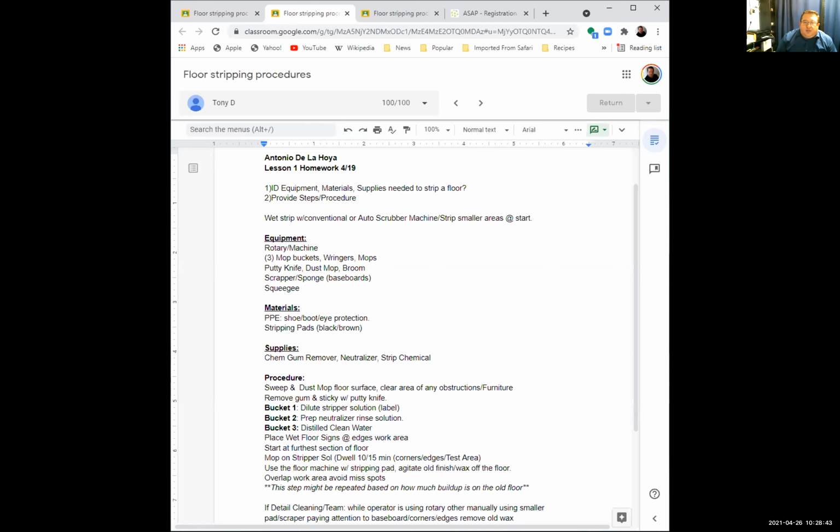So let me wrap up with the school on the MP room. Here's a way that you can learn how much square footage there is. There are two ways to measure it if you don't have a measuring tape and you want to cheat. They're a little more difficult, but I'll tell you the tricks. If it's VCT on the floor, VCT is a standard 12-inch by 12-inch. Count the tiles on the wall one way, count the tiles the other way, and multiply them. That gives you your square footage, because each tile is 1 foot square.